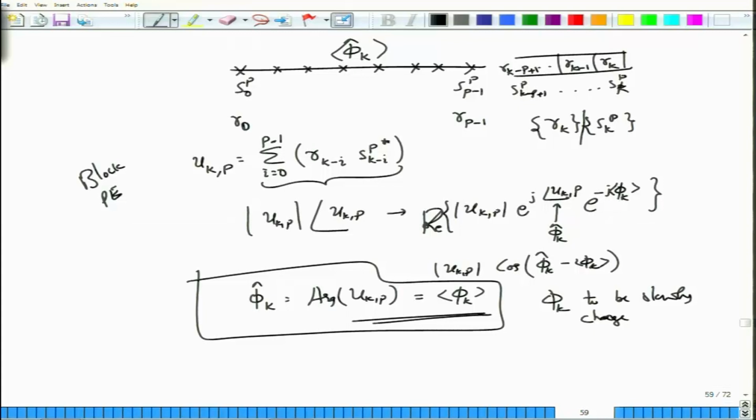The performance metric that you are looking at will again be the BER, and that will depend on the block length p. There will be some optimum value, as the BER is going to decrease and then increase. So, there is going to be some optimum value of p for which the BER is minimum, and you can work with that. That would be the optimum block length.